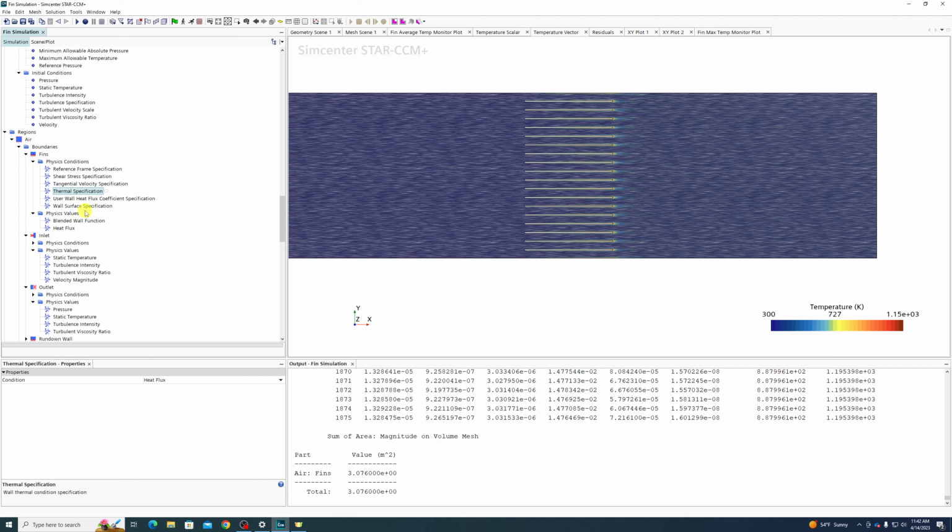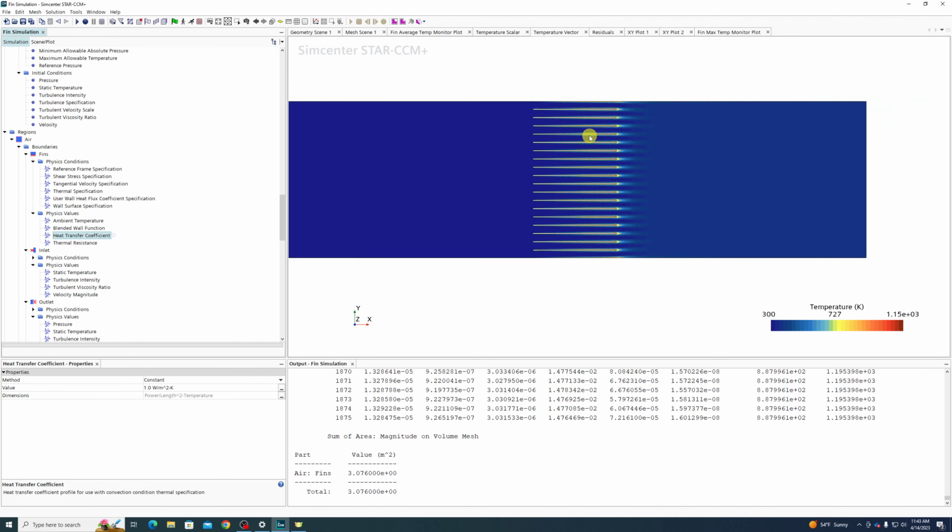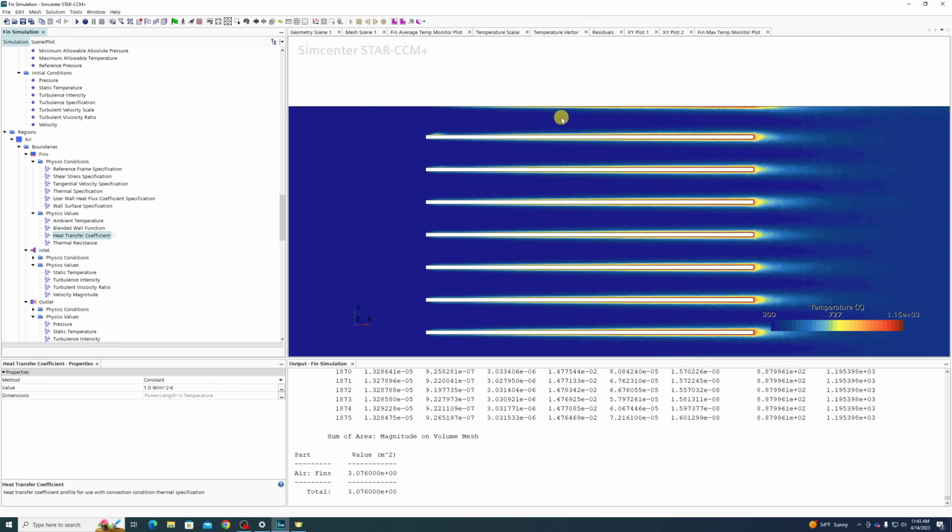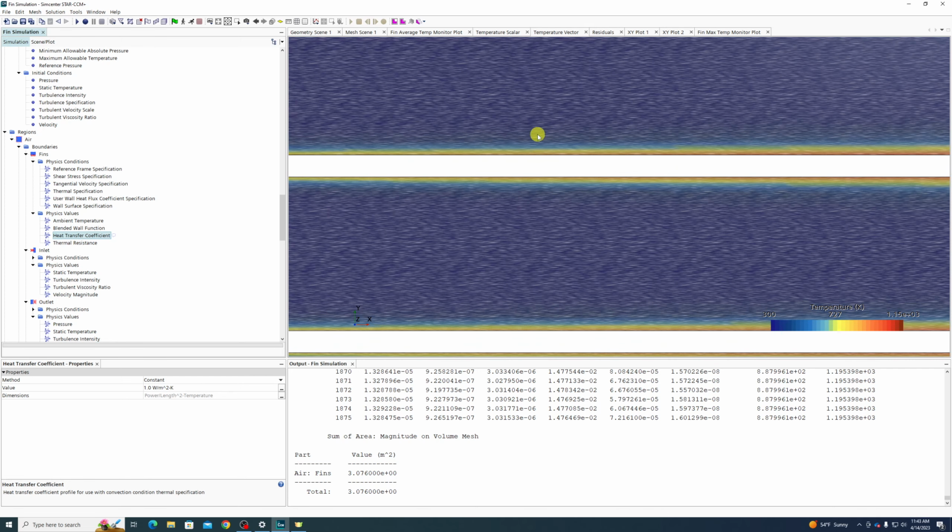But those are two types of boundary conditions. You can set a temperature, you can set a heat source, you could set a heat flux if you know your heat per unit area. You could also tell it, okay, back to before, adiabatic, there's no heat flow. Or you can tell it convection. Convection's a little bit interesting. It's a little bit counterintuitive because you might be thinking, oh, hey, this is the convection between this wall and this surface. It's not, actually.